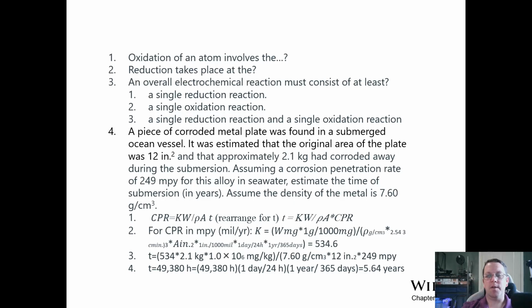But you're given the constant in mils per year, so thousandths of an inch, so you have to deal in inches, and then we get 49,380 hours, so we convert that up from hours to years, and we get 5.64 years under the salt water. In order to have a size change in total area to what we have with the final sample.